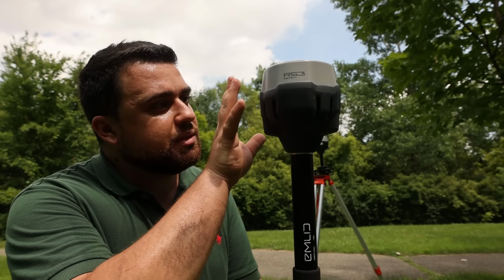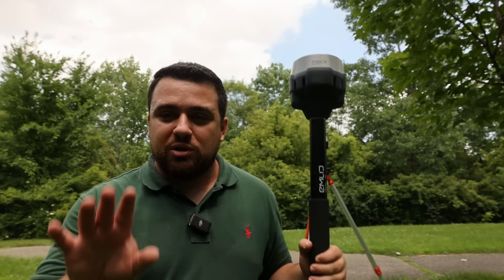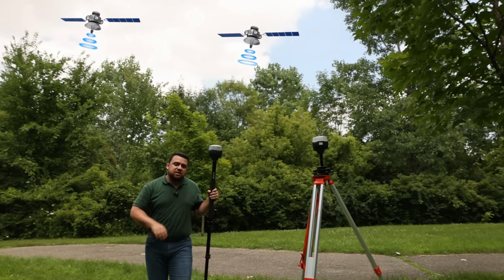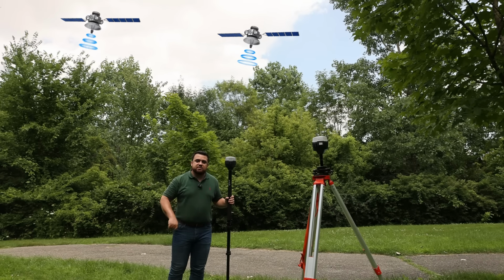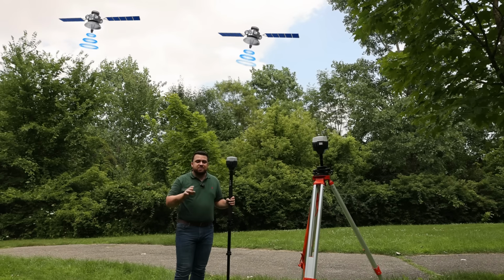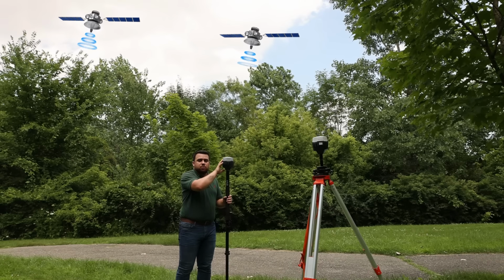So how does this GNSS receiver achieve centimeter level accuracy? Through the use of RTK. So let me break down what RTK is. In order to get RTK corrections, you are going to need 3 segments. The first is the space segment. These are your satellites that are up in the sky. You must have a clear, visible sight to these satellites from your receivers.